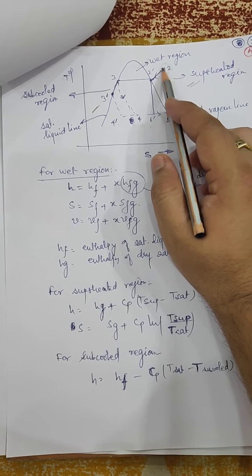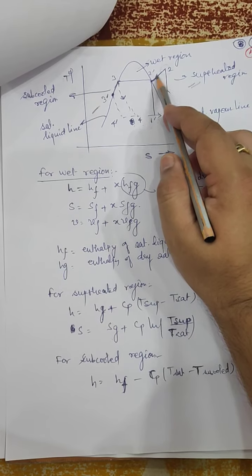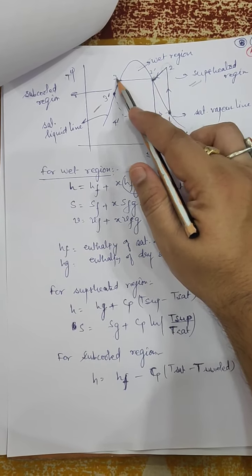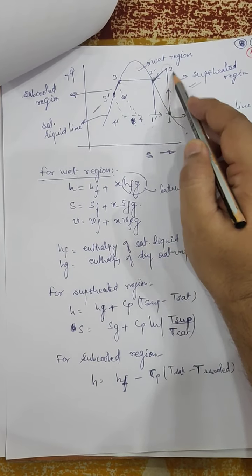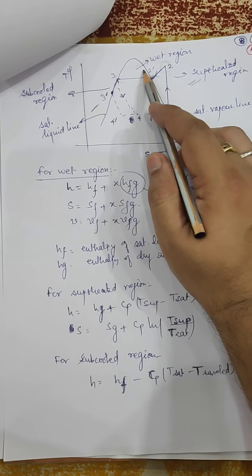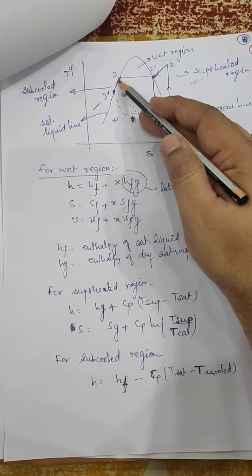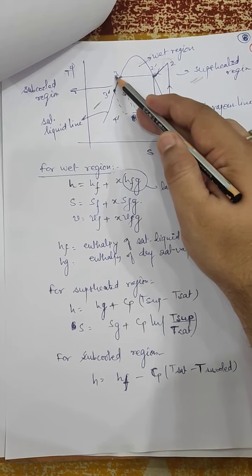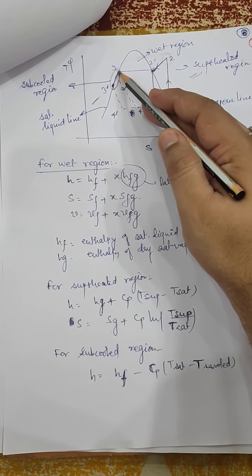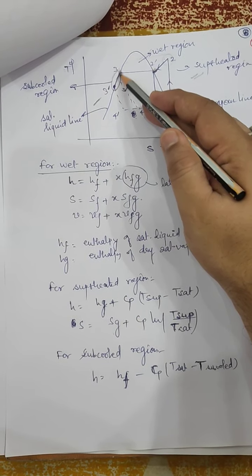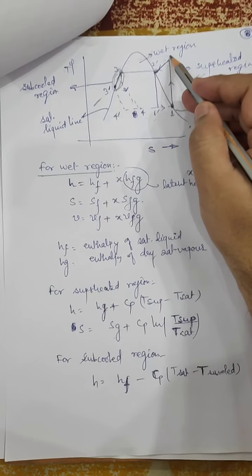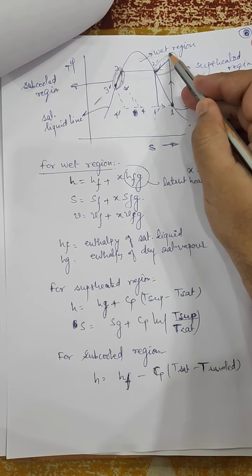It goes through the compressor, whether a single acting compressor or multi-stage compression, to point 2, then it comes here at 2 dash, again at the saturation curve. This whole portion is the condenser portion where the heat rejection takes place. 2 dash to 3 is your condensation where the heat rejection is taking place. Now again 3 to 3 dash is your subcooled region, where the temperature of the saturated liquid drops again. So this is your degree of subcooling. This one, 2 to 2 dash, is known as the degree of superheating.